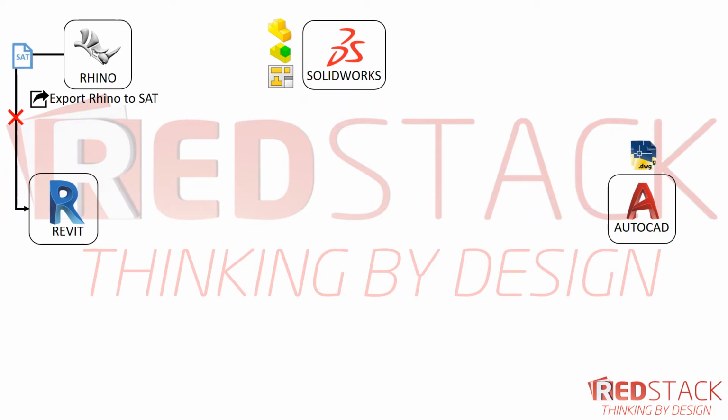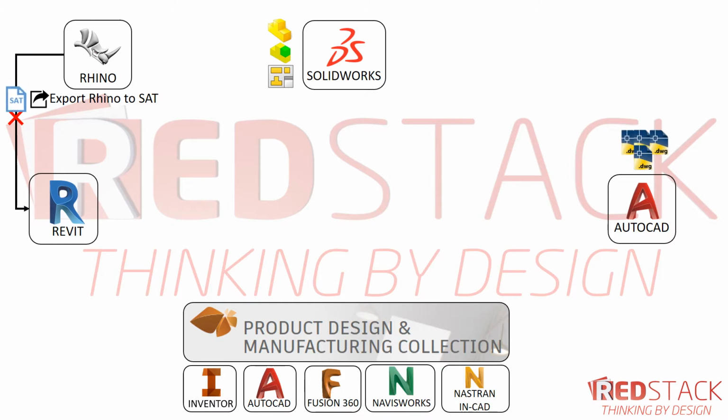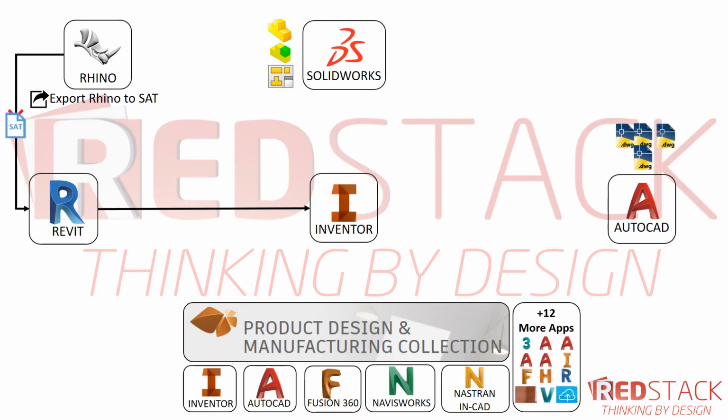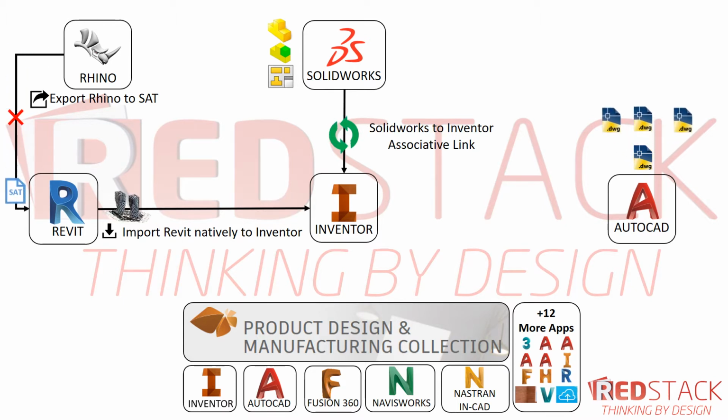Now let's see what happens when we start introducing the Product Design and Manufacturing collection from Autodesk. The collection comes with Inventor, AutoCAD, Fusion 360, Navisworks, Nastran, and about 12 other apps. So let's drop Inventor right in the middle there, and let's see how this workflow changes. So now I can drop in Revit projects natively into Inventor. In terms of Solidworks, Solidworks has an associative link with Inventor, so I can place my 3D model straight in Inventor from Solidworks, and if the Solidworks model changes, it automatically updates inside of Inventor.